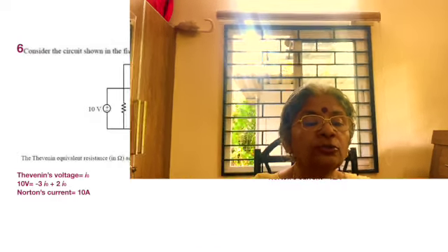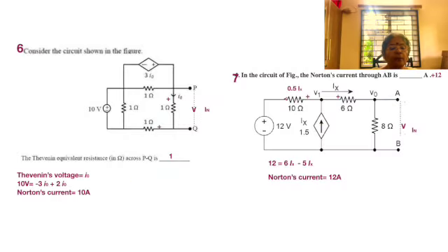Okay, moving on to the sixth problem. This is a little complex, but at the same time not so much. All the simple problems have been picked up for this first session in the fourth section of the circuit analysis that we're doing. I suppose you have already noticed that there's a voltage source 3I0, which is dependent, and I0 is the current flowing through the 1 ohm resistor. We also have another 10 volt source on the other side, which is independent, and a network of 1 ohm resistors.